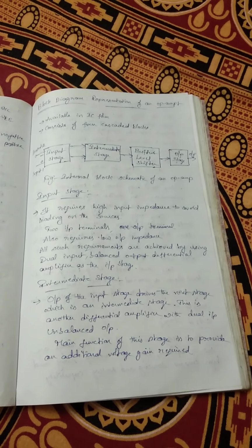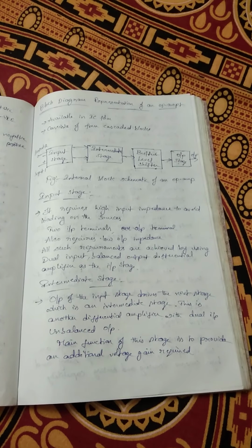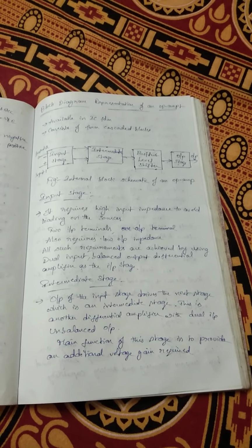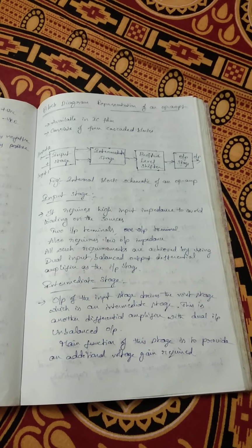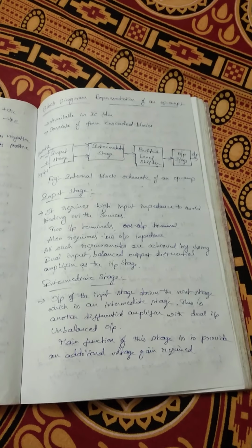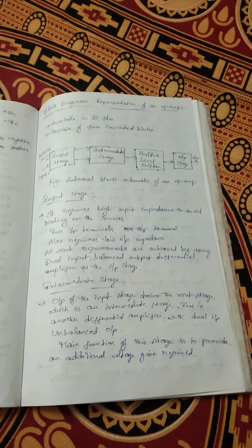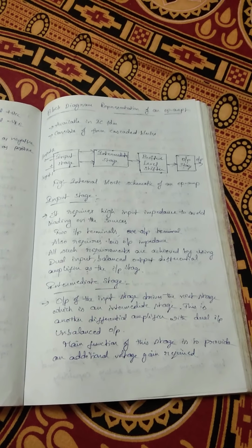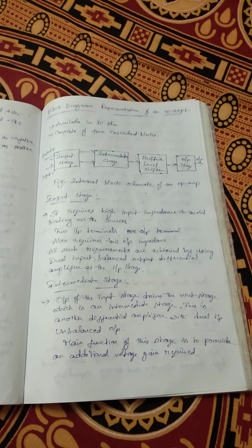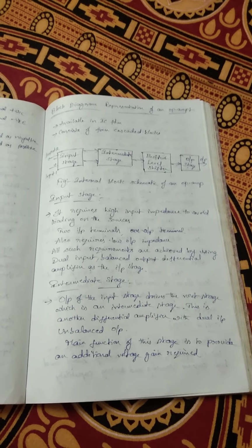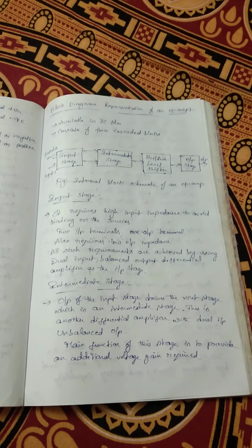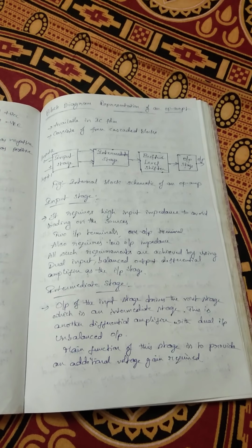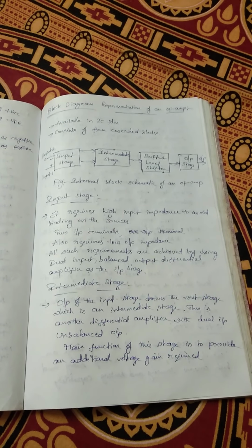Such a high DC voltage level may drive the transistors into saturation. This may further cause distortion in the output due to clipping. This may limit the maximum AC output voltage swing without any distortion. Hence, before the output stage, it is necessary to bring such a high DC voltage level to 0 volts with respect to ground. So, the level shifter stage brings the DC level down to ground potential when no signal is applied at the input terminals.